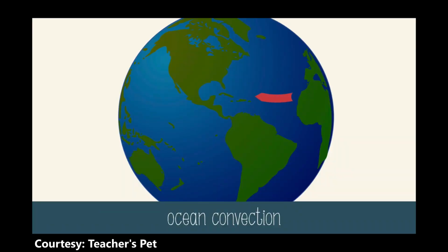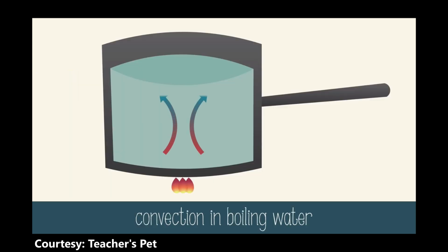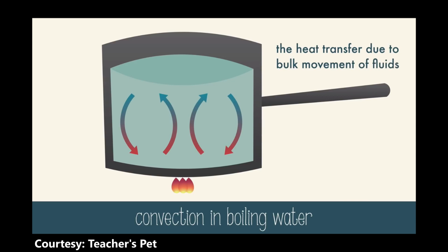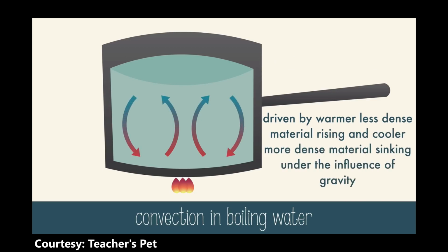Convection is the transfer of heat through a fluid such as a gas or a liquid due to the movement of that fluid caused by differences in temperature and density within the fluid, which in turn create buoyancy forces. One of the main concepts behind convection is the idea of thermal gradients or thermal differences. When a fluid is heated from below, for example, the lower portion of the fluid becomes warmer and less dense than the upper portion, creating a buoyancy force that causes the fluid to rise. As it rises, it cools down and becomes denser, eventually sinking back down to the bottom, completing the convection cycle.